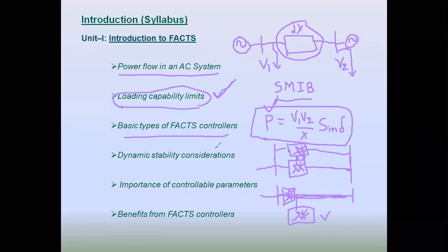Then based on generations, as in mobile technology we say 2G, 3G, 4G, and 5G is also coming nowadays, with new technologies introduced based on bandwidth and downloading capacity, similarly here we classify generations. The first generation FACTS controllers generally have a simple electronic switch and a capacitor or an inductor to control either reactive power or active power, in series or shunt.